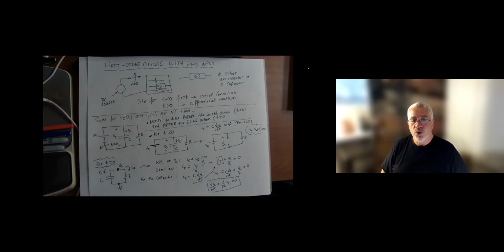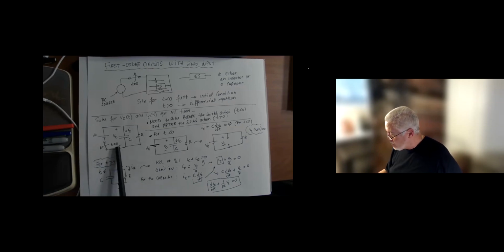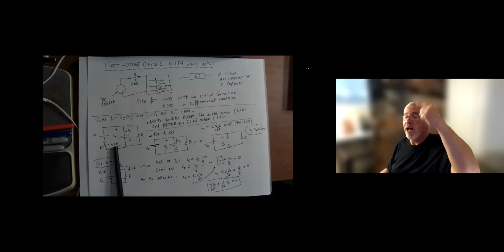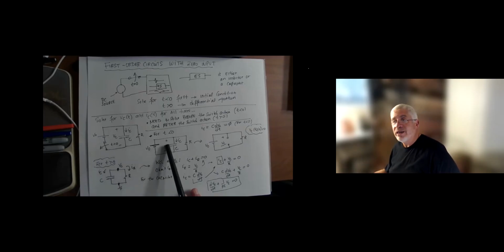Okay. So that's the process. So I'm going to review this a little bit, and then we'll go back to the PowerPoint slide. Again, when we have a circuit with a switch, we need to note the switch time. The switch time is important, and whenever you see a switch, it should clue you in. I need to solve the circuit before the switch, and I need to solve the circuit after the switch action. And we also solve the circuit sequentially because we need the initial condition.